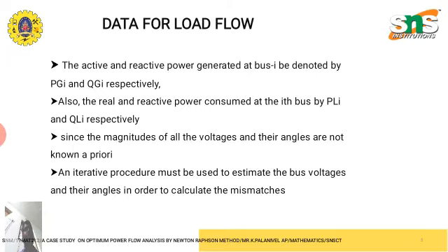For the load flow studies, we consider a system which has two generators and three load buses. We define bus 1 as the slack bus while taking bus 5 as the PV bus. Buses 2, 3, and 4 are P and Q buses. The line impedances and the line charging admittances are given. Based on this data, the Y-bus matrix is given. The matrix is to be noted here.